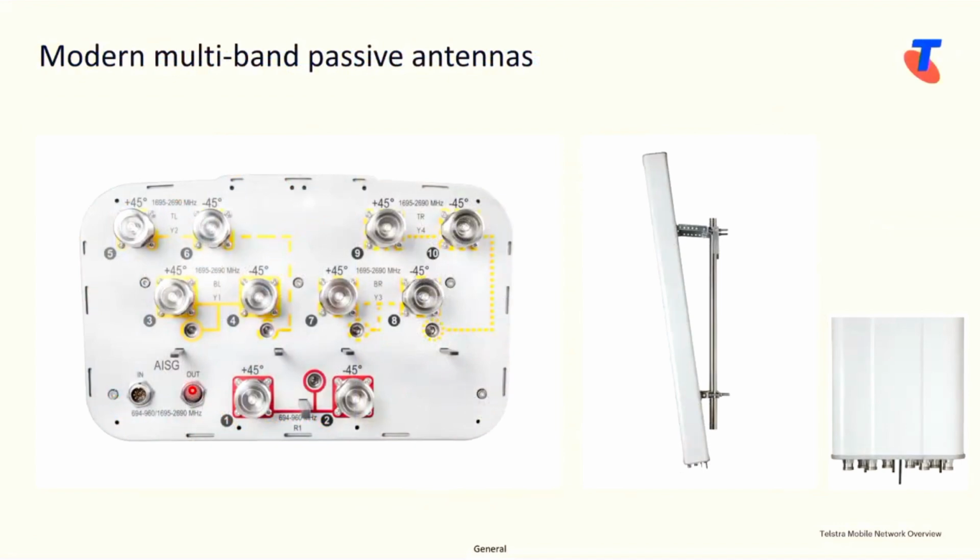All right, now the antenna looks pretty simple, but a little bit more going on inside there. So this is the actual antenna that's up there, and it's a multi-band antenna. You can see here we've got 4 high band ports, and we've got 1 low band port. These antennas can be tilted remotely. So we've got this AISG interface here, which allows us to control internally some stepper motors that change the phase and change the tilt of those antennas electrically.